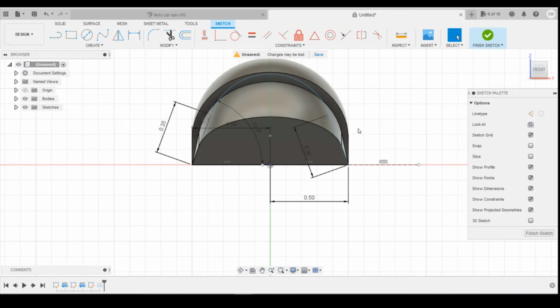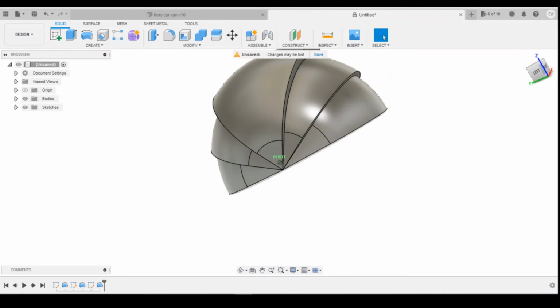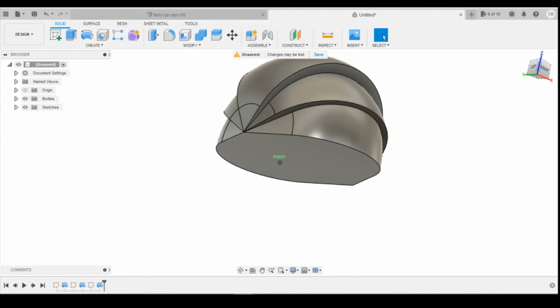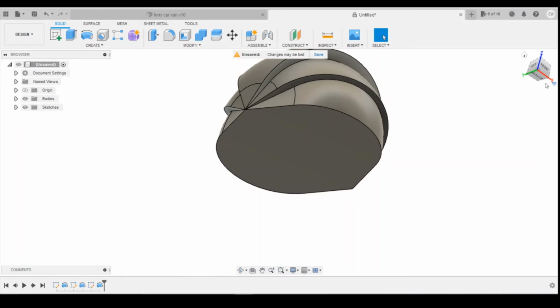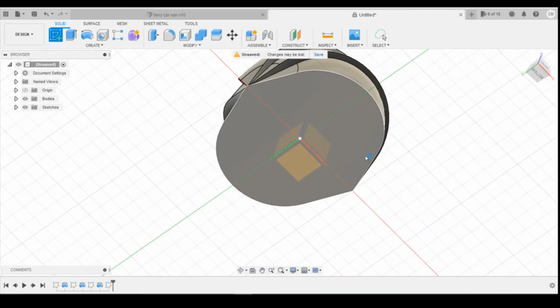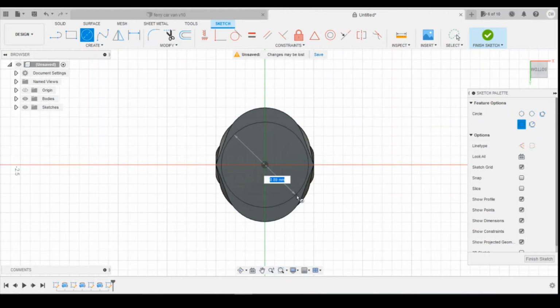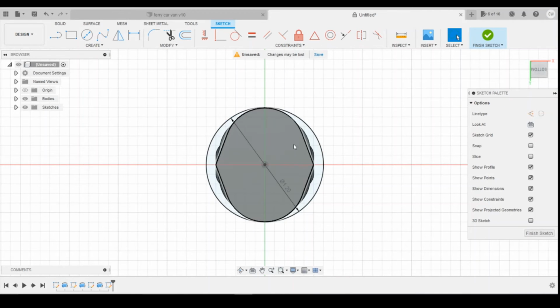So okay. Finish sketch and then we'll have a look at that. Okay, that's giving us the profile I think I'm after, and I just want to create a circular base here. Create on the bottom surface, use the midpoint as our constraining point, and then we're going to create a circular base. So it's 1.2 millimeters, looking at that in diameter, and then I can select those profiles.